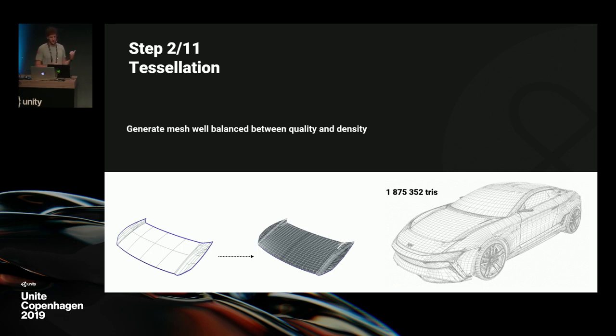So this car model here has a specific part naming convention, as I said before, and we can use that to automatically determine the tessellation precision parameter per part typology. For instance, we can define that the core body should have a higher precision than the chassis, or interior parts should have an even higher precision, because in Unity later, maybe the camera is meant to be very close to these parts, so we need accuracy.